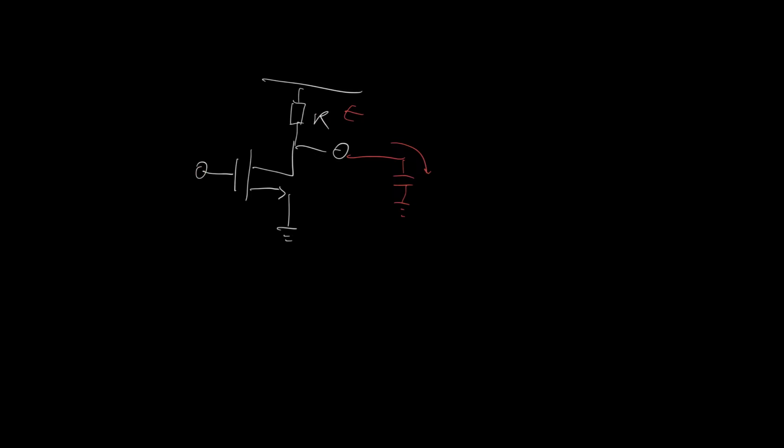So how do we choose R? Where we're heading is we want a variable resistance here that varies depending on what the input is. If the input here is a logic 1, then this FET is conducting, and so we don't want a small R here to waste energy. We want a very large R. If on the other hand the input's a 0, this FET's off, and we want this R to be very small in value to allow lots of current to be output here. So we want R to change. In fact, ideally, we want R to be replaced with a voltage-controlled switch.